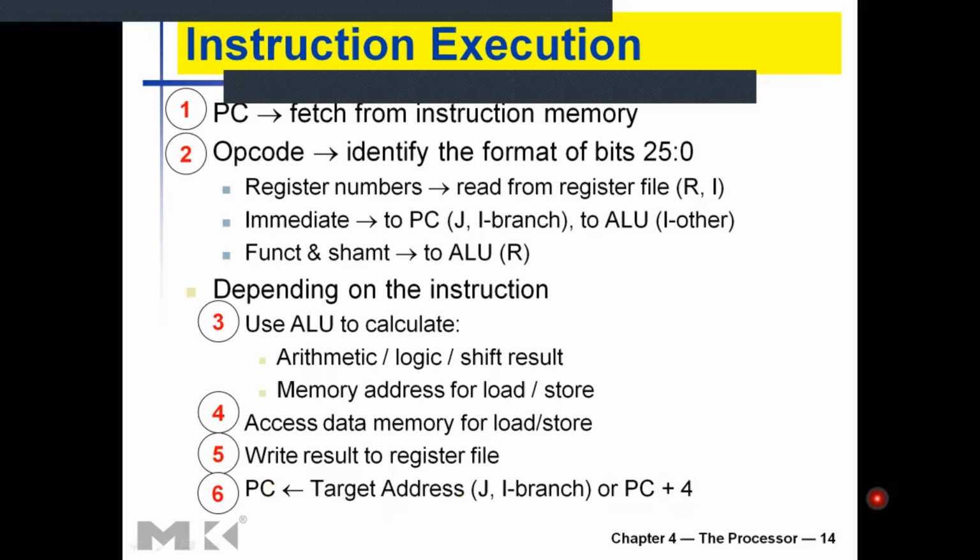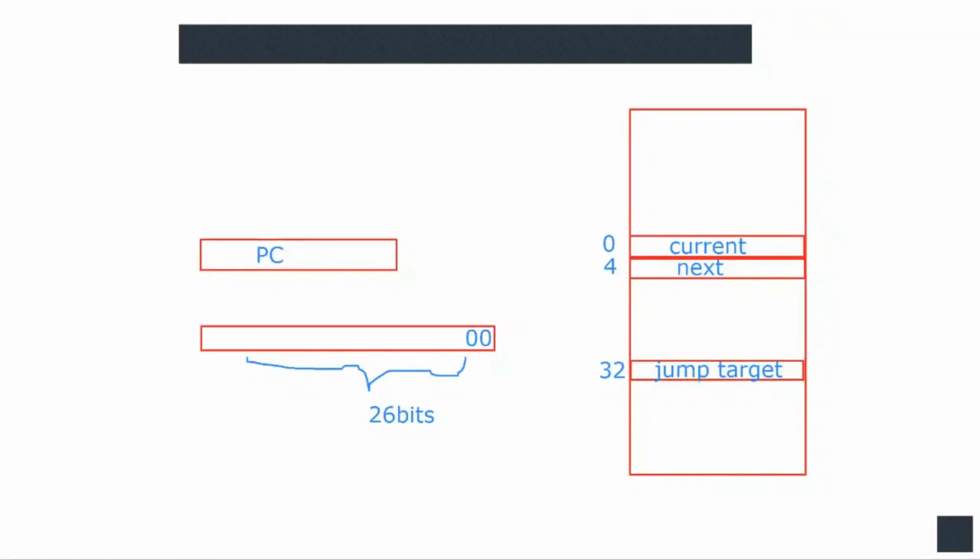Someone asked a question about byte addressing versus word addressing, so I'll quickly try to explain it. Here in the whiteboard example, we know that addresses here used increments of 4. Why did we do that? Because each word we have here is 32 bits wide, or 4 bytes wide.